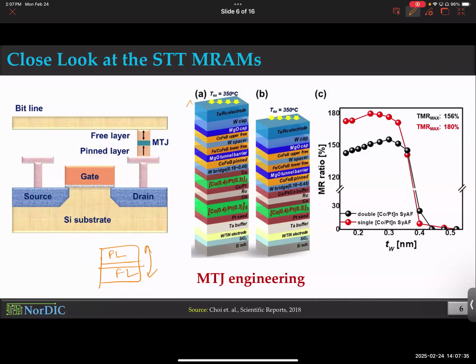Once you have that, imagine, I don't know whether this is it, but this could be one of those MTJs that have multiple levels, right? So apparently, by switching certain levels, you could have resistance 1, resistance 2, resistance 3, and resistance 4, which you could use to represent 0, 0, 0, 1, 1, 0, 1, 1. That is the other motivation.